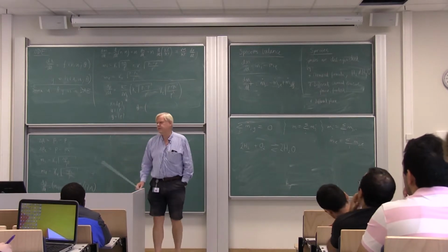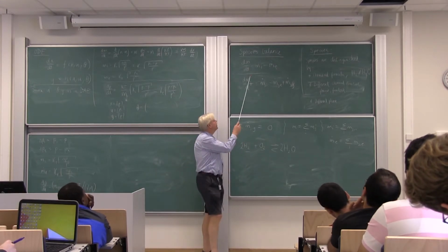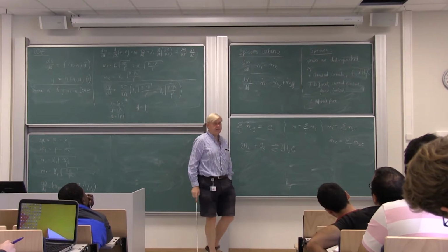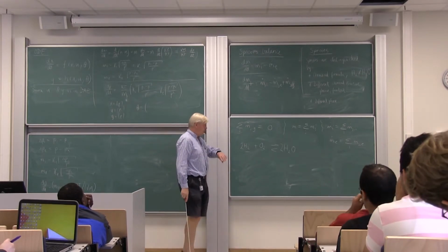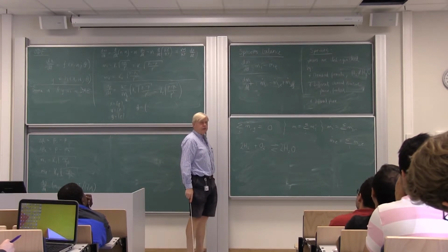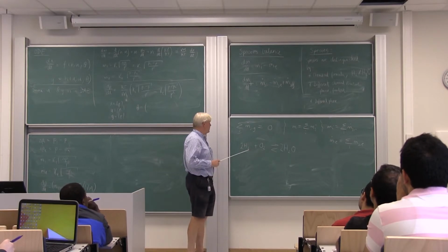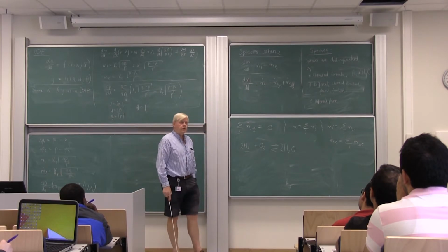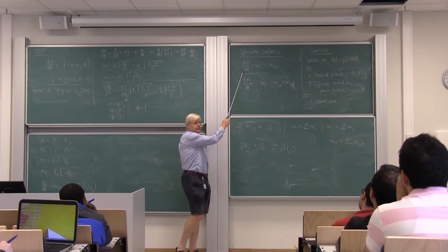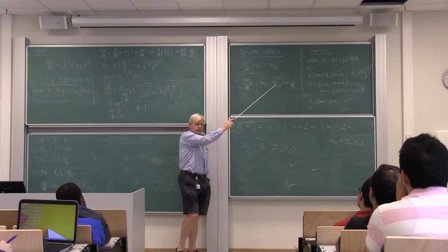We have an alternative, however. Remember that the total balance is still valid, and the total balance comes from summing the 3 individual species balances. So alternatively to having a species balance for hydrogen, oxygen, and water, we could have a total balance. But since the total balance is a linear combination of the others, we can only use 2 other ones.